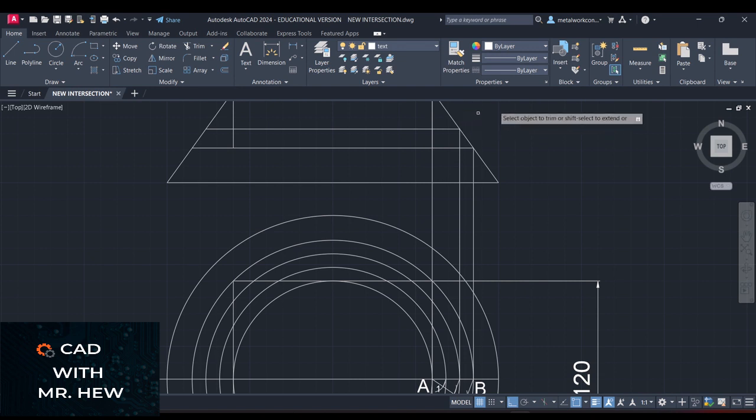As I said, if you're using a traditional T-square, or set square, pencil, French curve, erasers, you would just leave the line, because that would be a 4H construction line, right? But you know, AutoCAD, we want to keep it clean, so I trim it. You could let it stay, but the drawing looks neater. All right, so having drawn this there now, look what I did. Can you guess what's the next step?